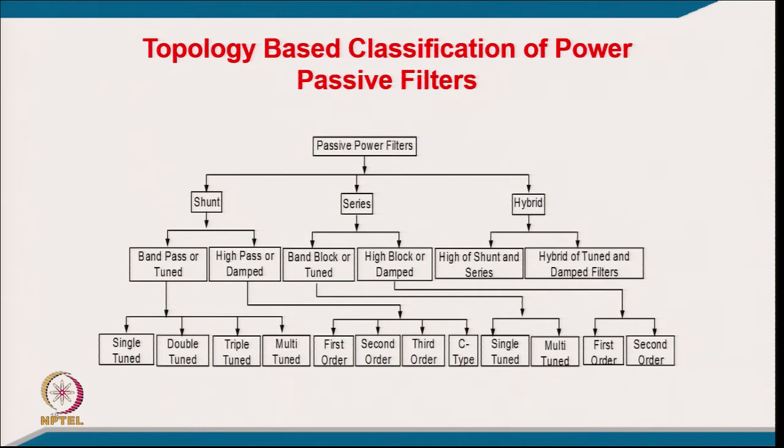So, we design in such a manner that the quality factor of the inductor is quite high, so that the losses are not much. But it only takes care of one or two particular harmonics for which these are tuned.